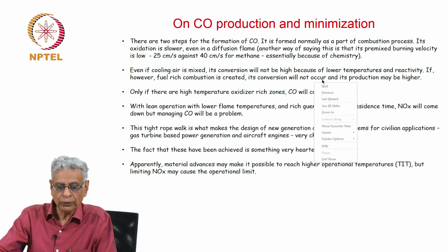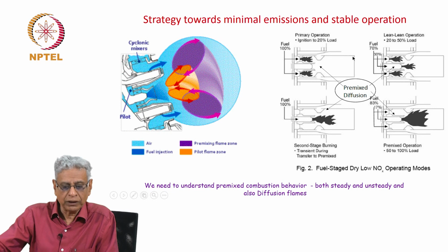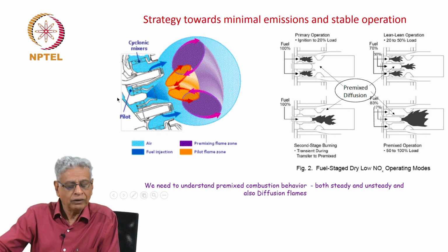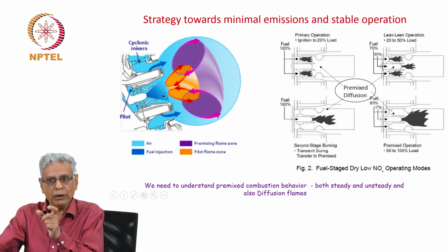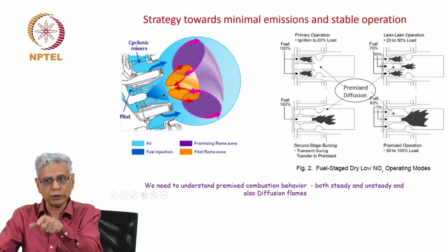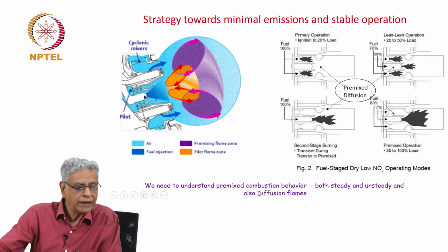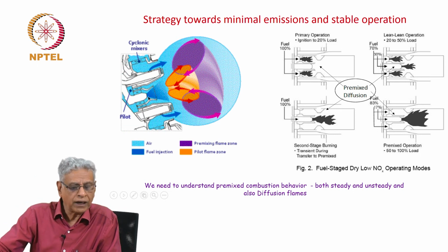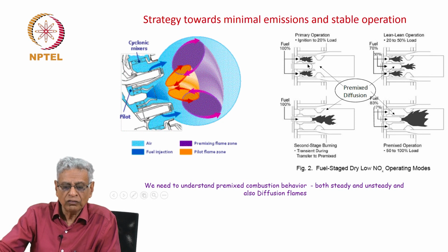Okay. So, let us go to the aspect here. I will explain to you just one of the elements. Rich quench is what is used in one technology, which is not shown here, but I will explain to you. In this, as I mentioned to you, you have the central zone which carries fuel, diffusive mode of combustion, but the combustion in this and this are premixed.